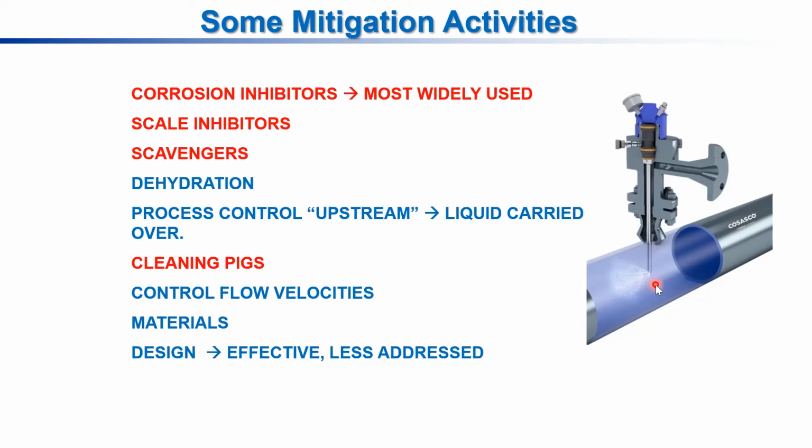I love quills more than spray nozzles because spray nozzles may plug more easily than quills. So here you have a quill, and the quill will generate enough turbulence in this area to enhance the mixing. That is the key for chemical treatment to work. The mixing. The better it's mixed, the better it will work. And in many cases, you may have to inject, in addition to a corrosion inhibitor, a scale inhibitor, etc. So how do I know that it's working?